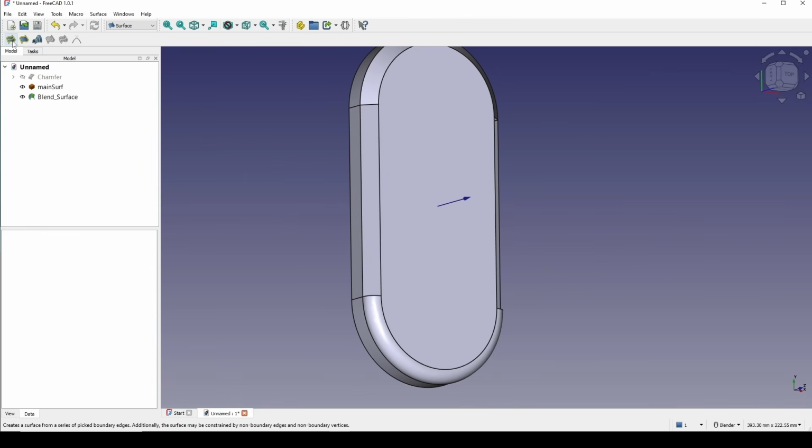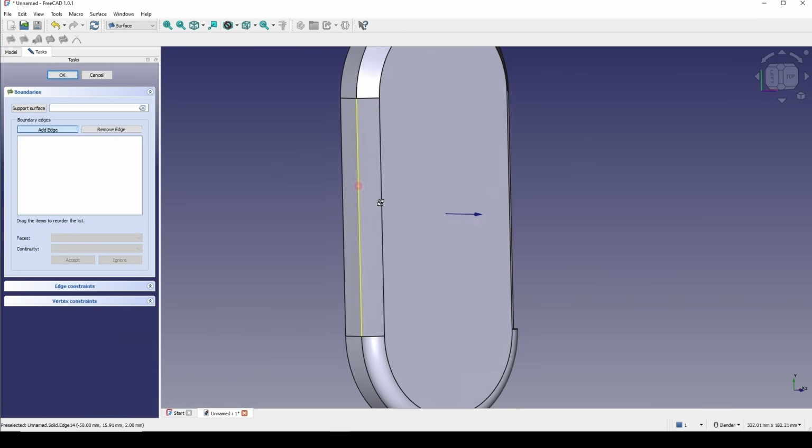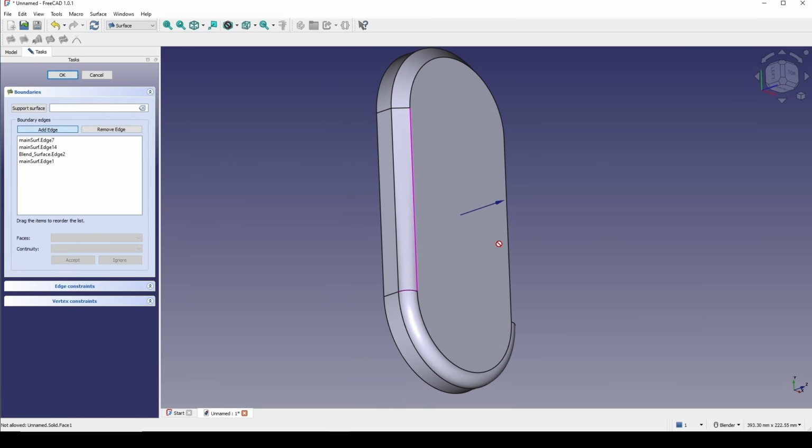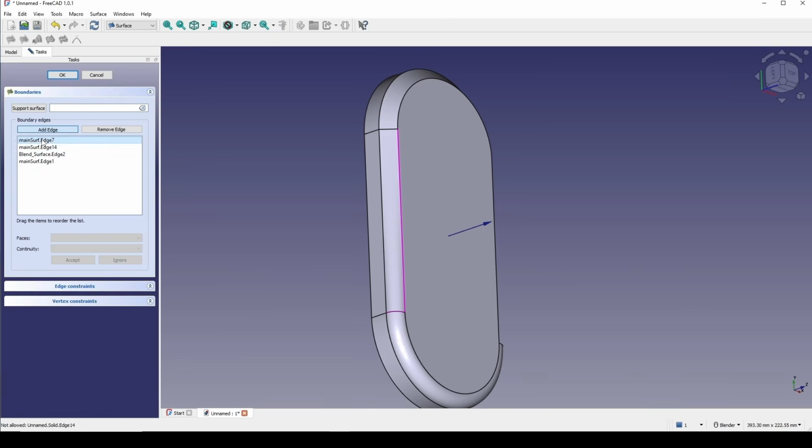and click on the filling tool and start to fill from this edge and select edges in sequence. So I go inside the first edge, which is this one, and I go to selecting the face and choose the G1 continuity, accept. Now we just add the tension in here. I double click on the plane surface edge, which is this one, go to the face and G1. Okay.